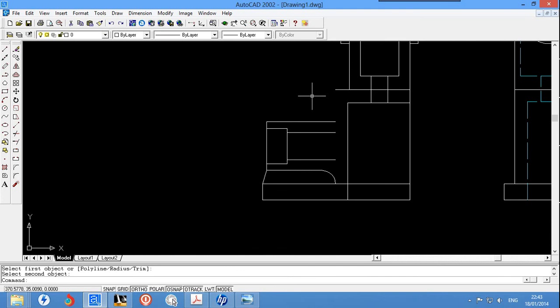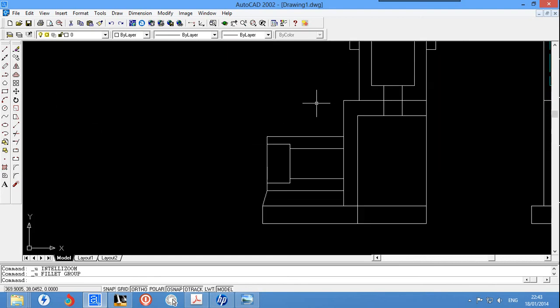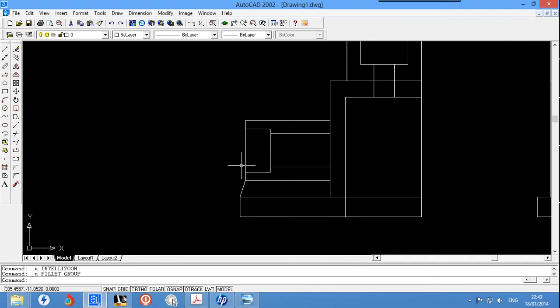So we have curvature here. Here we have a command called fillet. This fillet gives us the ability to make this curvature. So let's draw it, let's use it. Fillet between this and this. See, it makes like that. So we need to extend our line again.